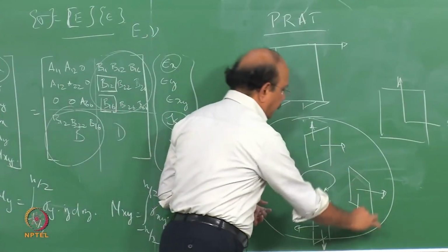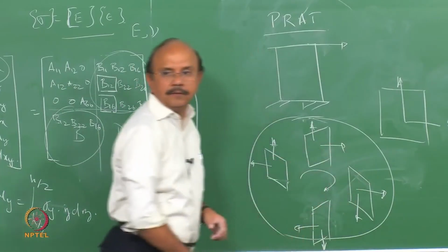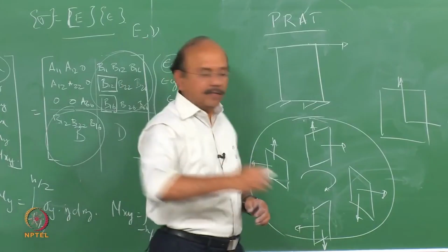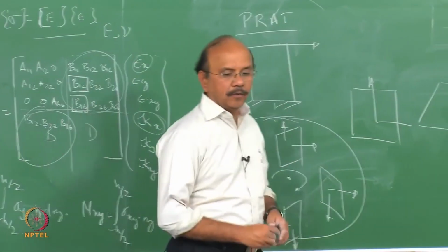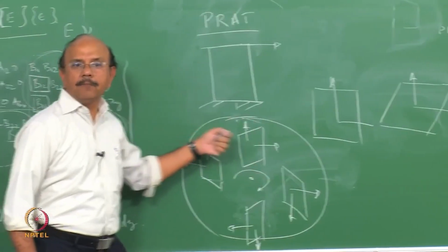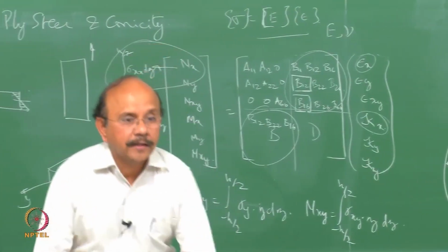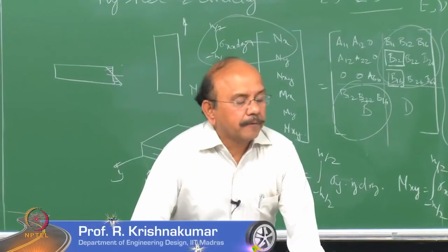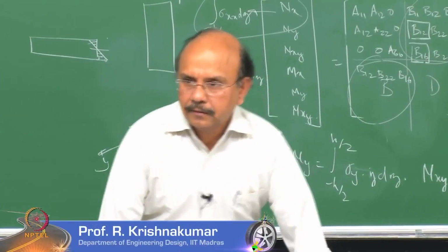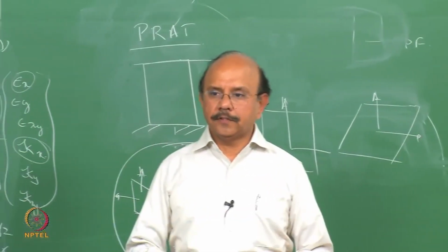So when you have perpendicular forces present, that results in a torque towards the center of the tire. This is the center of the tire, and so there is a moment that's acting. So this is another reason why there's an aligning torque when you're going straight. We'll come back to this, and we'll continue with this and the other derivations in the next class.